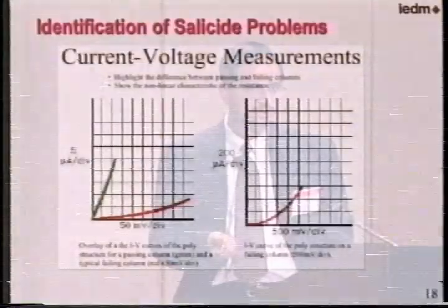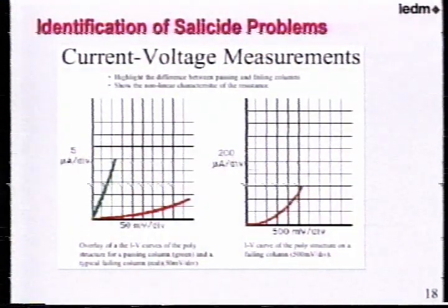Here is a simple example of the green line showing where the salicide worked well for an SRAM, red line where it didn't. Simple case, all of you know it very well. You are able to measure this red line, say, problem with my salicide, look at the NP transitions. You often look at the contact resistance on the butted transitions. You figure out what to do with your salicide. You, of course, can change your salicide conditions in the process. Some people even go ahead and widen the salicide a little bit, a polyline.